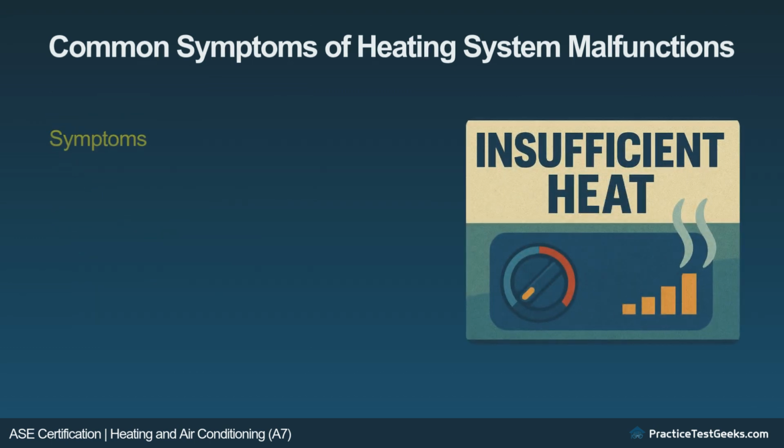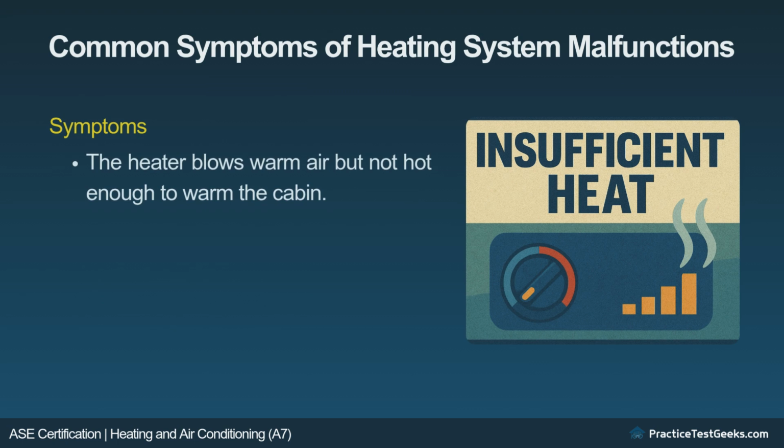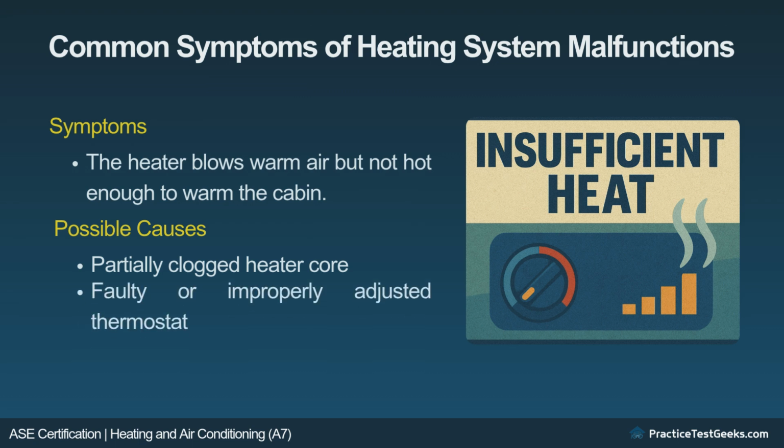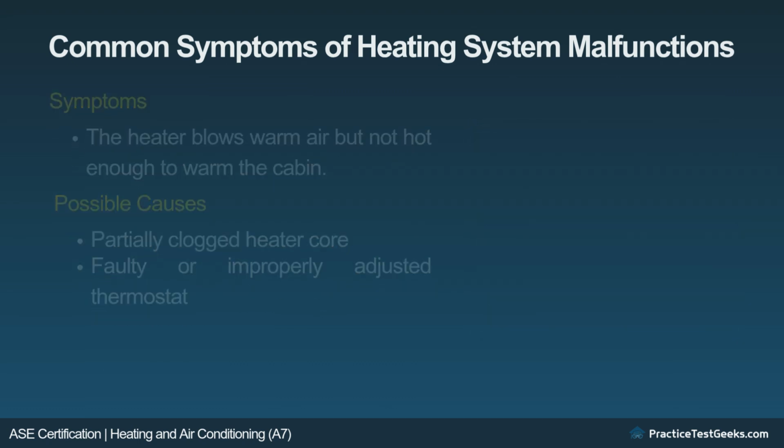Insufficient heat. Symptoms. The heater blows warm air but not hot enough to warm the cabin. Possible causes. Partially clogged heater core. A partially blocked heater core reduces heat transfer, causing lukewarm air to blow from the vents. Faulty or improperly adjusted thermostat. A thermostat that's stuck partially open can cause insufficient engine heating.